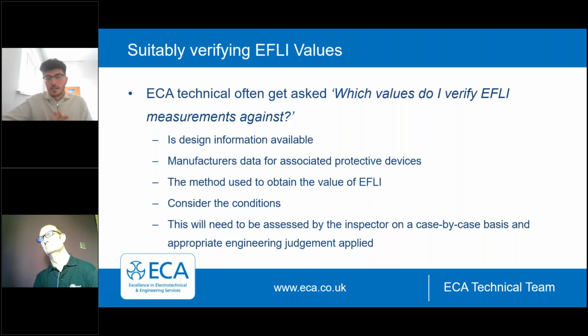You could say as a blanket approach, I'll just go safe and use the 80% values. That's fine. But what you've got to consider when you're doing an EICR is if those conductors are warm, you might not be able to achieve the 80% values. So it could be that you may be saying something's unsafe where you actually haven't considered the circumstances and the conditions.